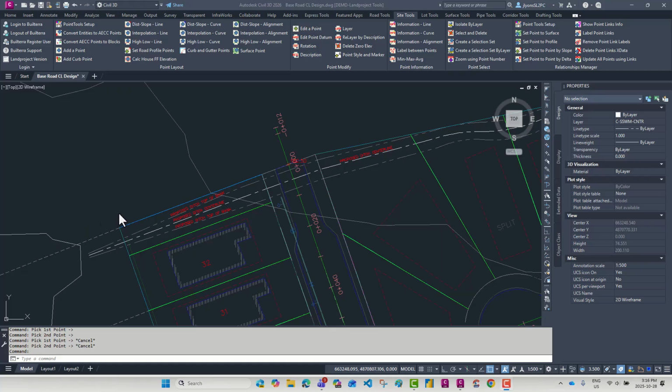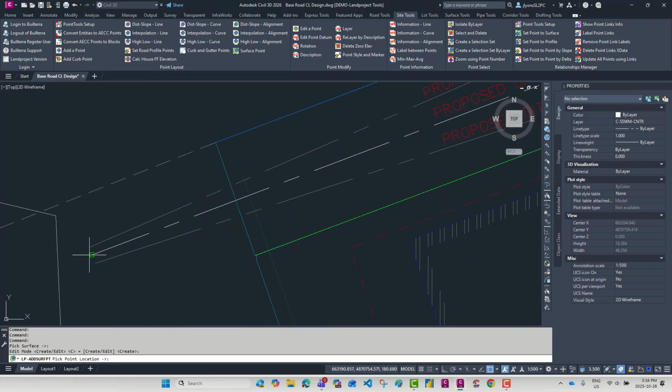In this demo, we're using three distinct tools to set design points along a curve object or polyline. All three tools are used to create or update grading points using a defined distance and grade or grade relationship along a selected polyline. This approach is ideal for layout-driven grading, where elevations are controlled by geometry rather than surfaces